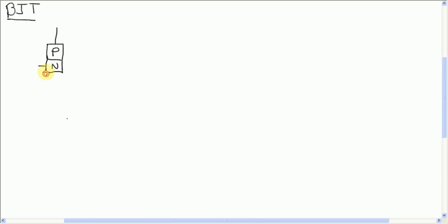Well, transistors aren't all that different. All that's happened with a transistor is we've added in this piece down here on the bottom. So we've now sandwiched an extra layer. So you have PNP, or of course the other option would be an NPN. And now we have two depletion regions, one through here, and one here. So there's two spots where there's a joining of the P and the N-type material, which gives us a bit more control over the current that flows through this.